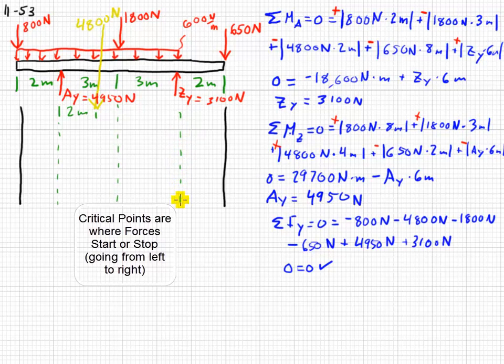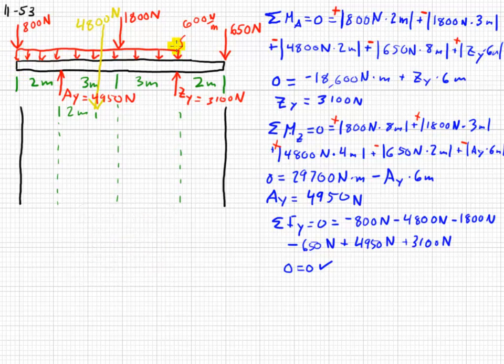Now note that I did not use the 4,800 Newton force showing here. This is merely a phantom force, only usable for the total of this distributed load, and very useful for finding the moments and the reactions, but not to be used for the actual diagrams here.